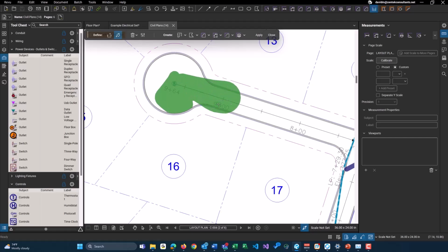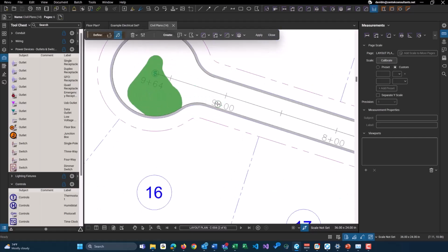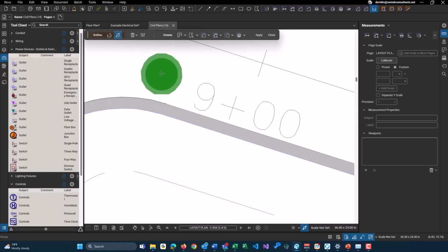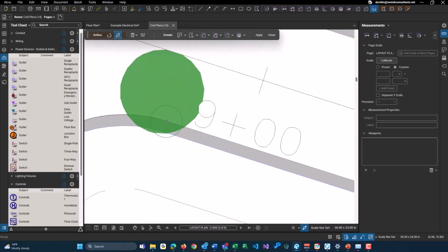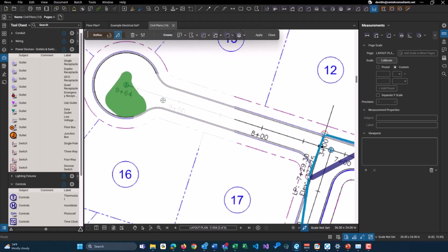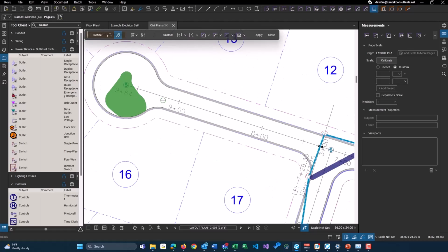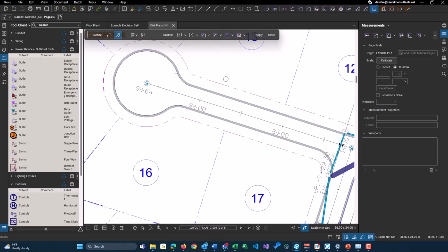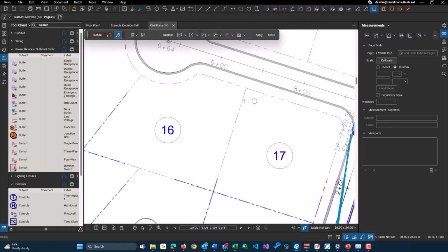And you color in the space. Looks like there's probably some type of line that's messing this up right here. Yeah, this isn't connected all the way. One little downside about the dynamic fill tool is if a room or area is not fully enclosed, it's going to escape.